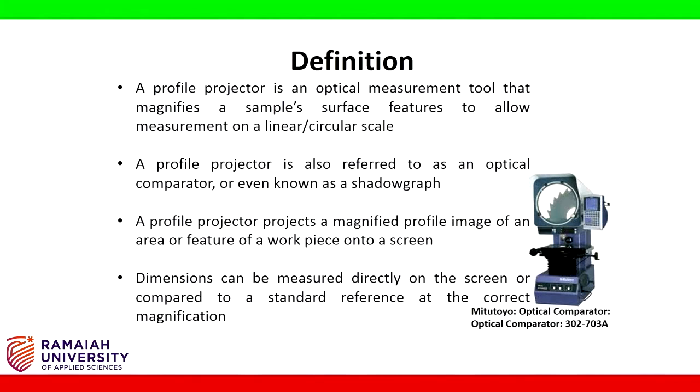A profile projector is also referred to as an optical comparator or even known as a shadowgraph. A profile projector projects a magnified profile image of an area or feature of a workpiece onto a screen. Dimensions can be measured directly on the screen or compared to a standard reference at the correct magnification.